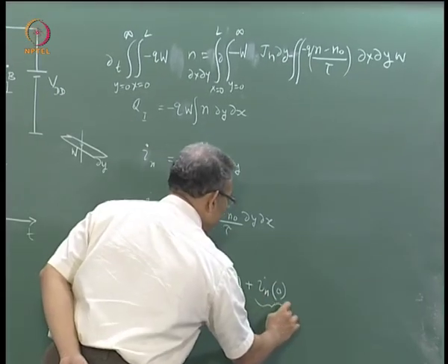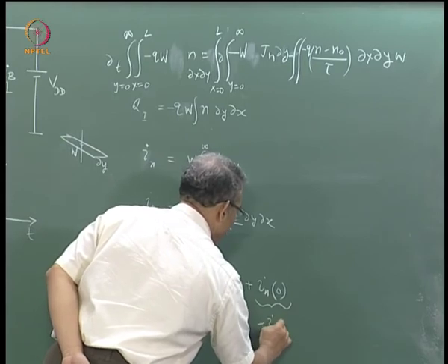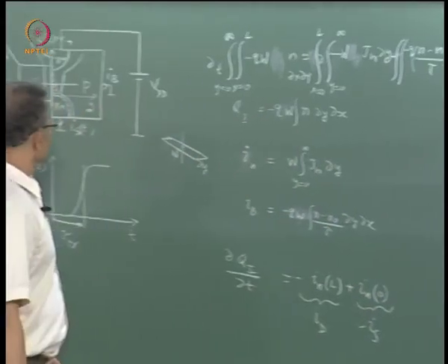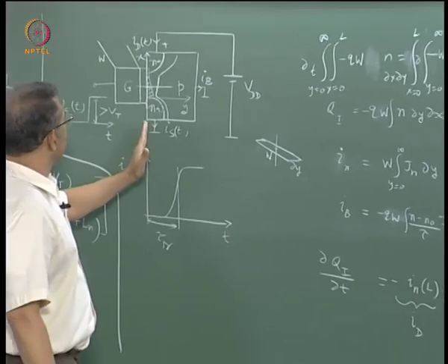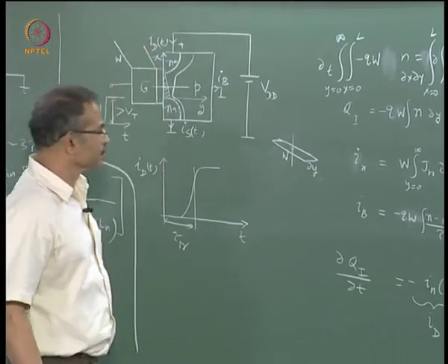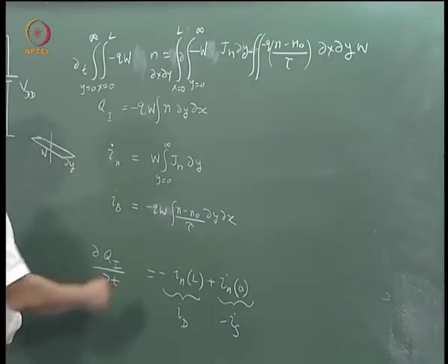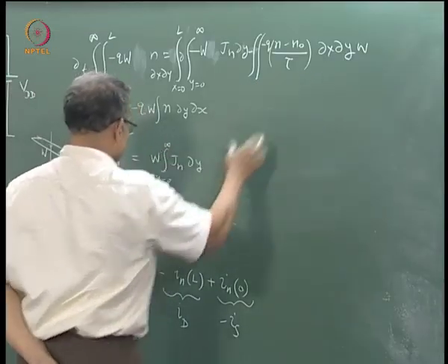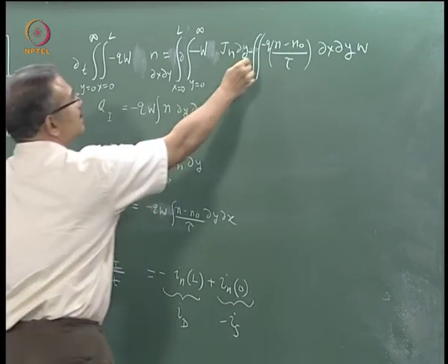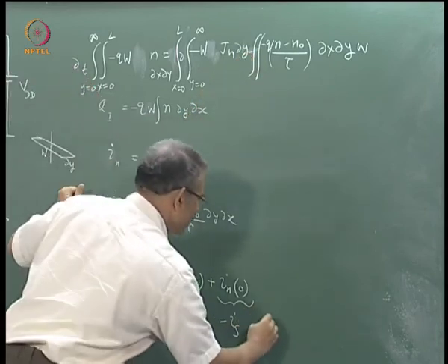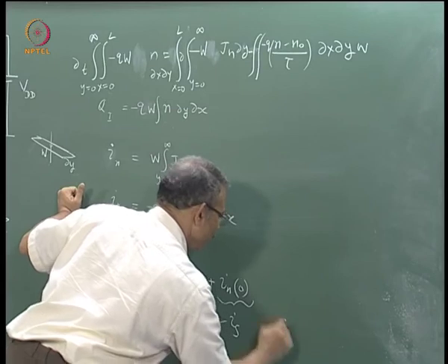Similarly this quantity can be identified as minus of Is, the source current, again downward, whereas your x is upward. Now what about this here? This current can be directly related to IB, with a minus sign, so you have minus of IB.